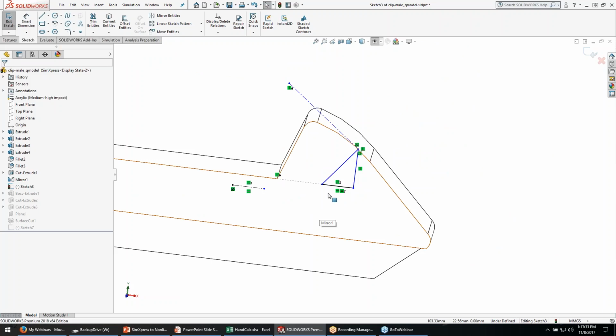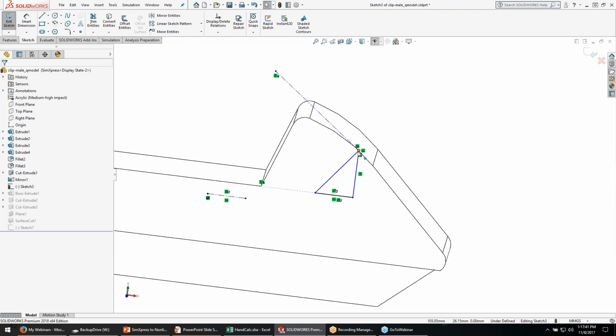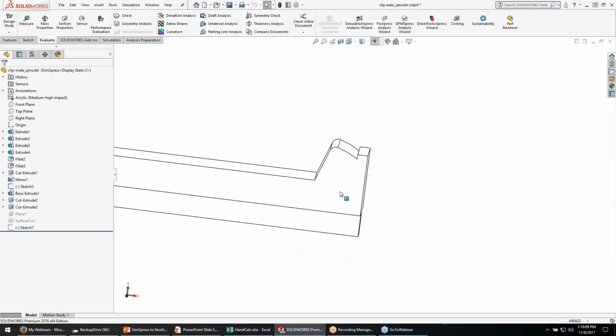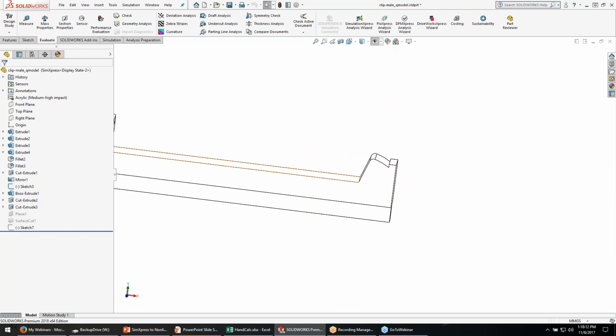Okay, so the main point here is you see how creative I sort of have to be to try to estimate where that final contact point is going to be. It looks to me that it's going to be right about here according to this estimation. And by the way, this assumption doesn't take into account the fact that this will bend downward and sort of changes this angle of this beam a bit. Maybe significantly, maybe not. I'm assuming that that's small. So it looks like that maximum force is going to be somewhere right around here. Okay, so that's where I'm going to model, if I discard these changes here, this little plate. I'm going to cut off the rest on the right side of the beam for a little bit later, but that's where I'm going to model a place where I can put forces in a moment. And that's where I'll measure the length of the beam as well.